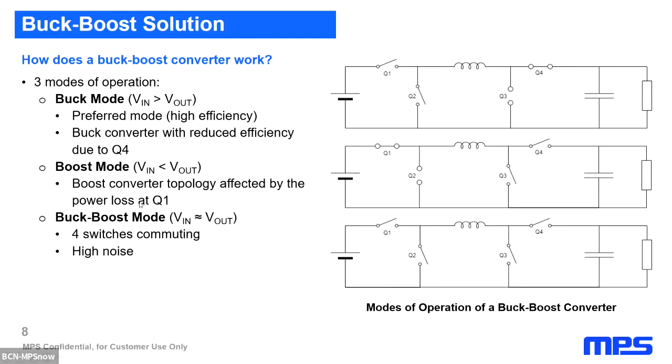Finally, we can also obtain a buck boost mode. In this mode, the output voltage is more or less the same as the input voltage, and the 4 switches are commuting. This mode of operation is not the recommended one because we obtain high noise.